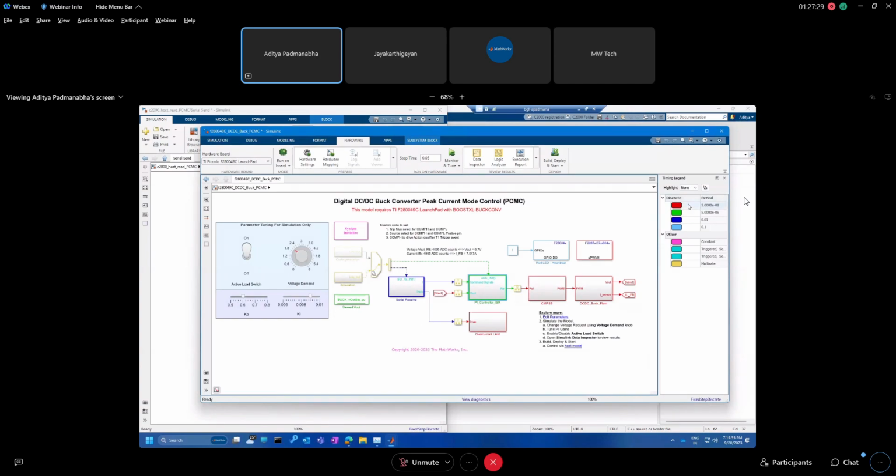In the simulation, the entire control loop runs at 200 kilohertz, or 5 microseconds. To simulate it properly, I need the plant model to be simulated at least 100 times faster, so the sample time for simulation is much higher.